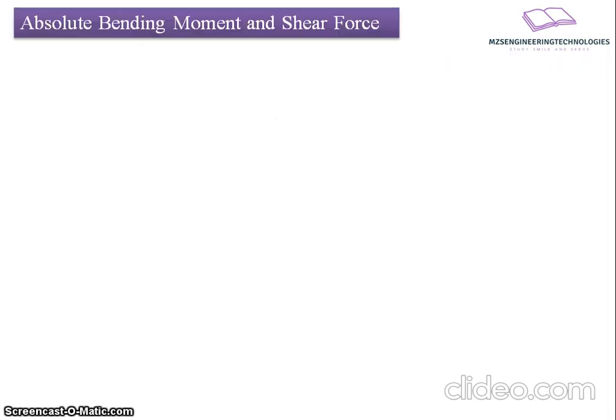Let's move towards the next concept related to absolute bending moment and shear force. We came across the statements maximum bending moment and maximum shear force, which is the maximum value of bending moment or shear force at a particular location or for a given loading condition. But in the case of rolling loads, loads roll from one part to another. At each position, they develop a response, thereby there will be a variation in the bending moments or shear force along the span.